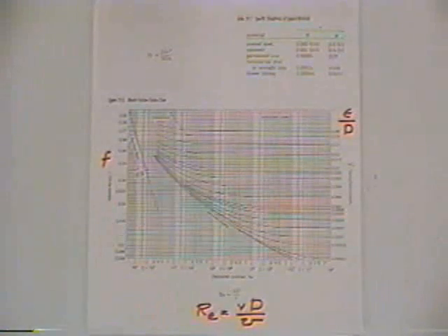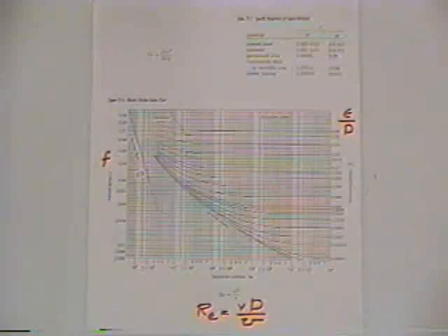And there are different areas of the Moody diagram. Another concept in fluid mechanics which comes into play here, which we mentioned very briefly in another application, is the concept of laminar versus turbulent flow. Laminar flow is where you've got smooth layers of flow, just smoothly flowing one layer over the other. Turbulent flow is random motions, as the fluid particles are going this way and that way in a random flow field.